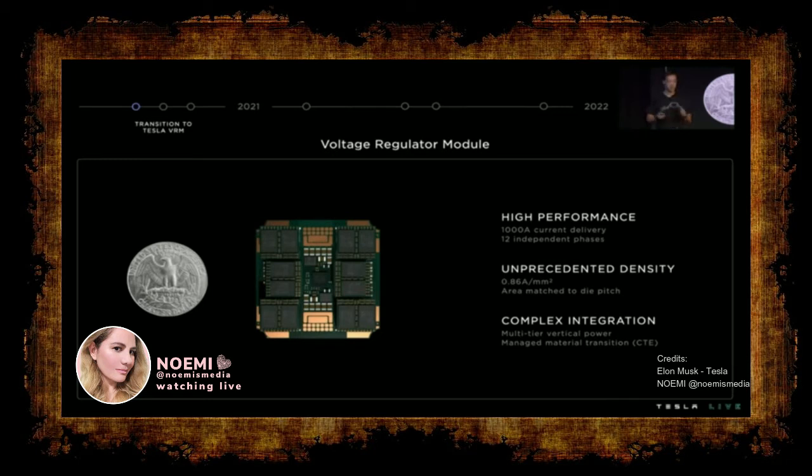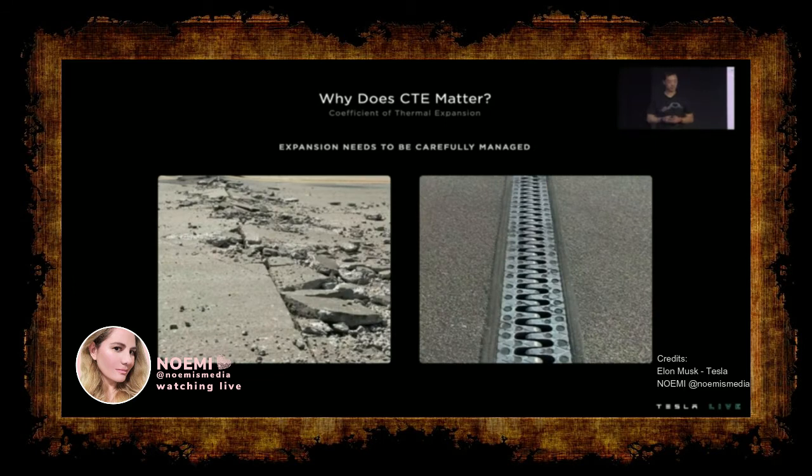And because there's a complex heterogeneous material stack-up, we have to carefully manage the material transition, especially CTE. Now, why does the coefficient of thermal expansion matter in this case? CTE is a fundamental material property, and if it's not carefully managed, that stack-up would literally rip itself apart.